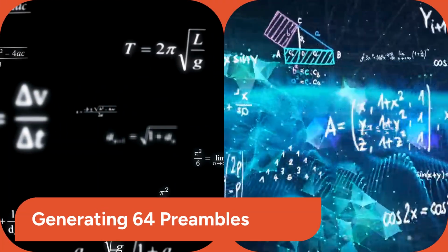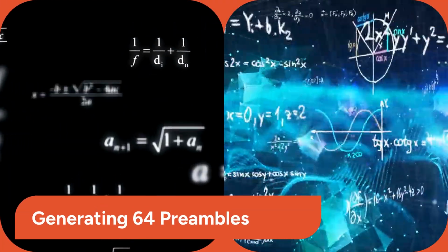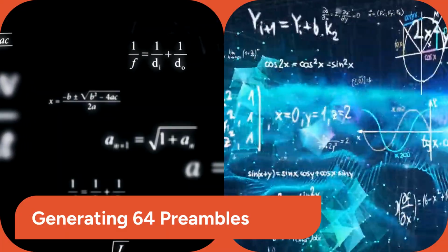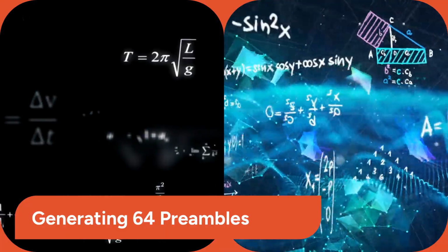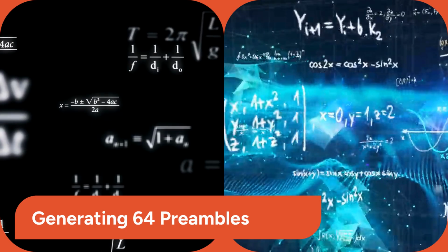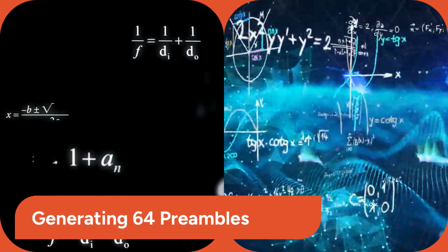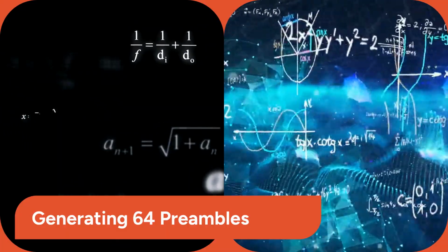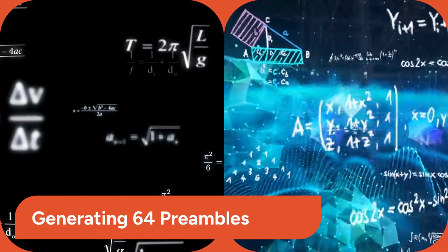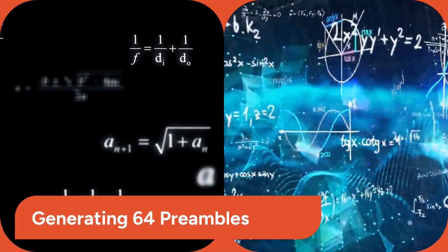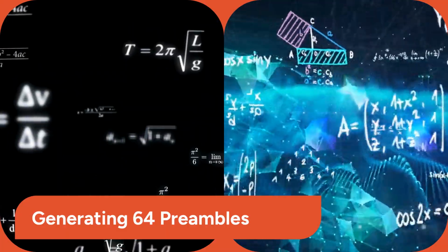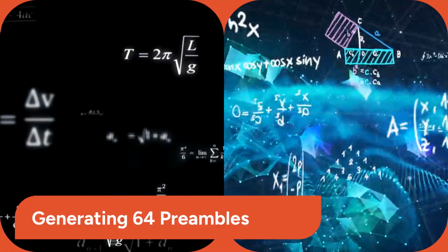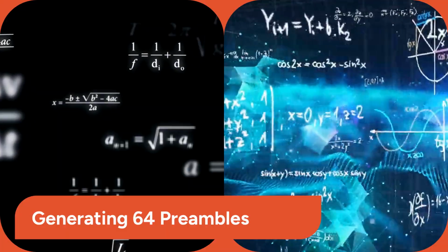The zero autocorrelation property is our key to extremely precise timing detection, like a perfect puzzle piece fitting into its slot. The low cross-correlation property minimizes interference when multiple UEs attempt access simultaneously, ensuring signals from different users don't completely clash. Each cell needs a set of orthogonal preambles. LTE provides 64 distinct preambles. These are not 64 unique ZC sequences. Instead, the E node B generates them from just one or a few ZC root sequences, designated by a root sequence index. The remaining preambles are generated by applying a specific cyclic shift to that root sequence.